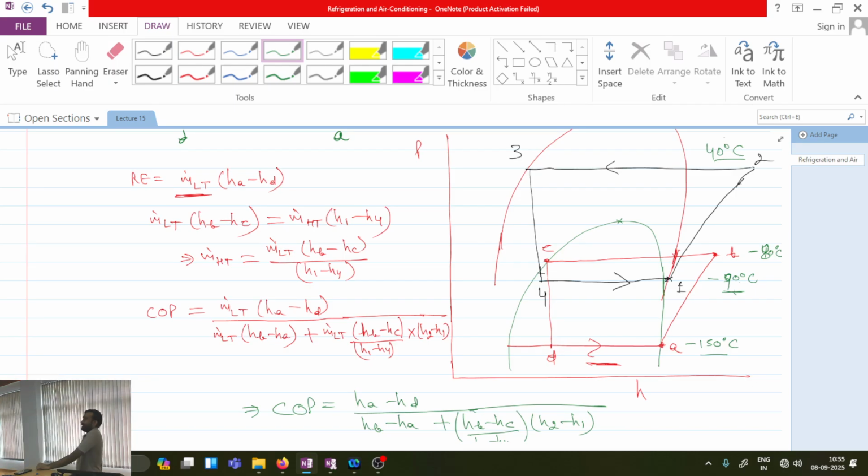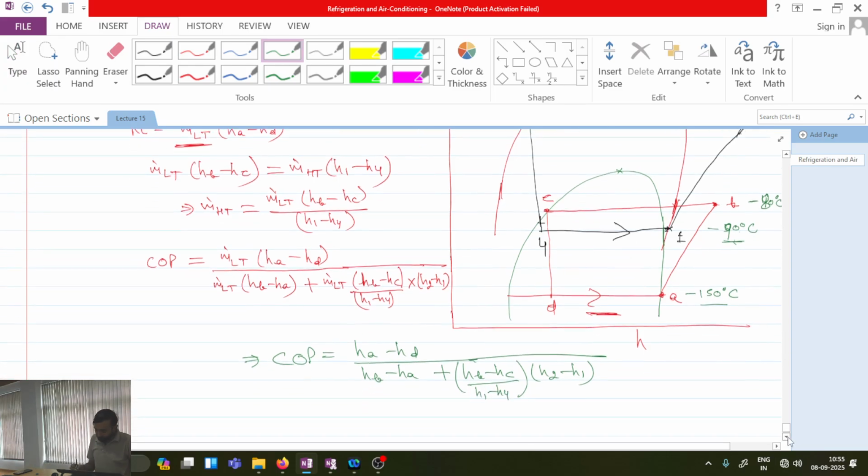So it means that depending upon the requirements of the temperature, any cycle, LT or HT, can have multi-compression systems. Is this point clear? And whenever there is multi-compression, there will always be flash chamber, liquid subcooler, etc. All the components will be coming into picture.